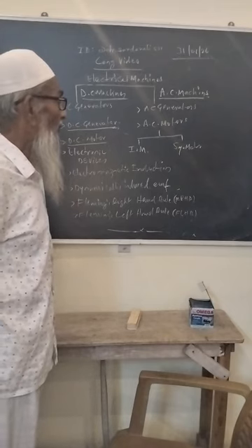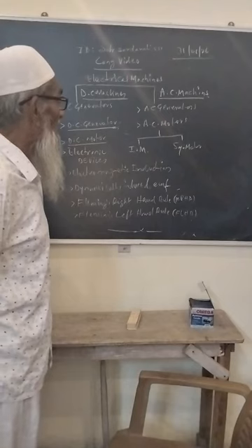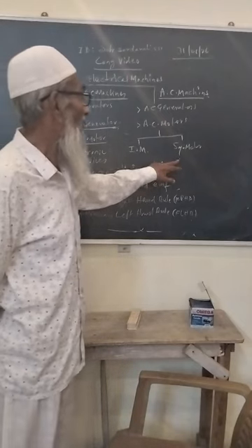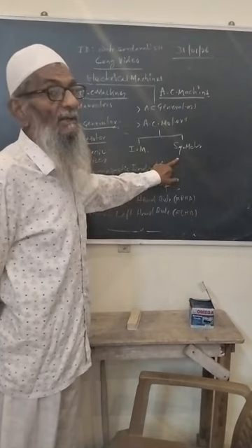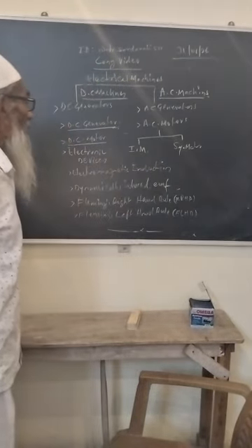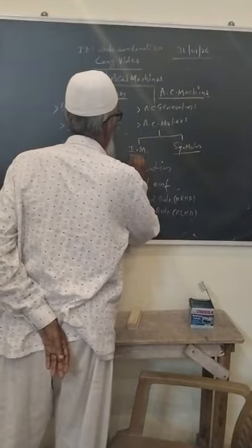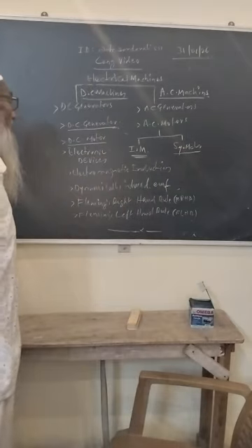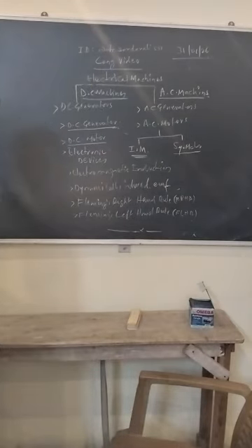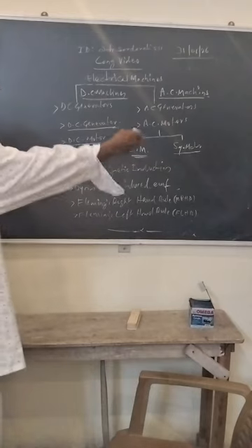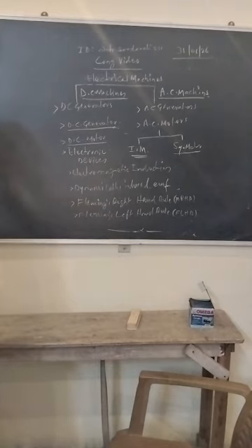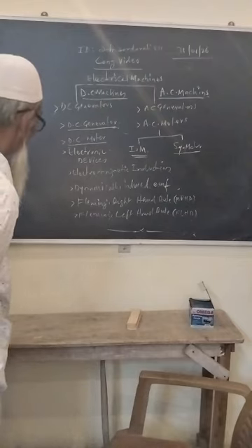Their speed, of course, all of a sudden will not be changing, and they will be very costly in manufacturing and operating also. That's why they will be rarely used in the industries, whereas the induction motor will be used commonly in the industry, and they will be manufactured from fractional HP to thousands of HP, whereas there are the standard synchronous motors. Anyhow, in detail we will be discussing later when their terms come.